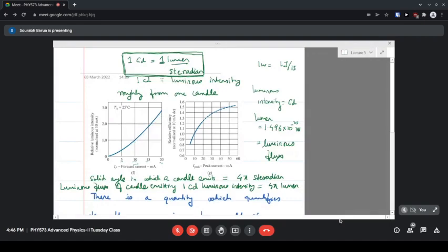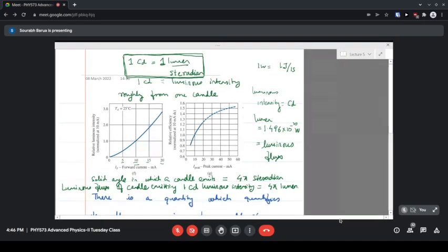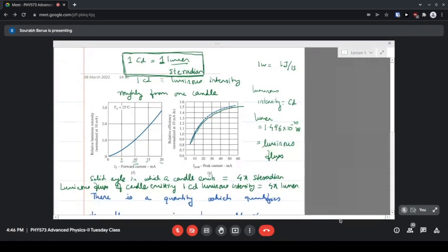That is because of the efficiency, that means per unit electrical energy, how much electrical energy is being converted to light energy. That fraction will fall down as you increase the level of current. So after some time, because the relative efficiency is going down, the brightness will saturate.